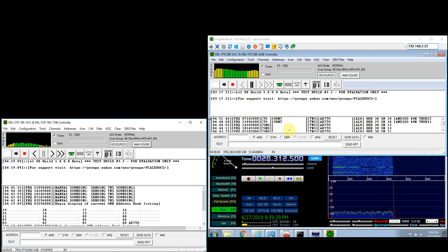One last thing I should mention is that because we're talking about putting these SDRs co-located with transmitters, you're probably going to want to use a transmit receive switch or diode protection of some kind on the SDR input, so that when somebody keys the transmitter with an antenna just a few feet away, typically you don't want to blast the input of your SDR with that kind of signal.